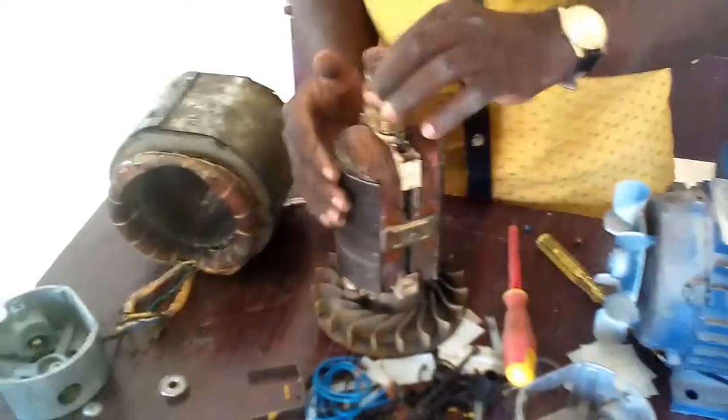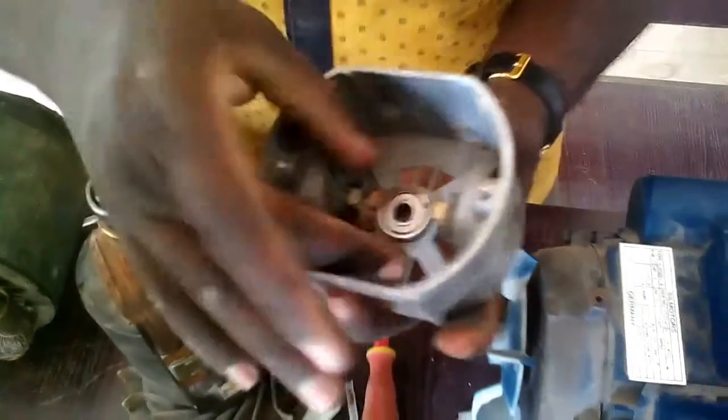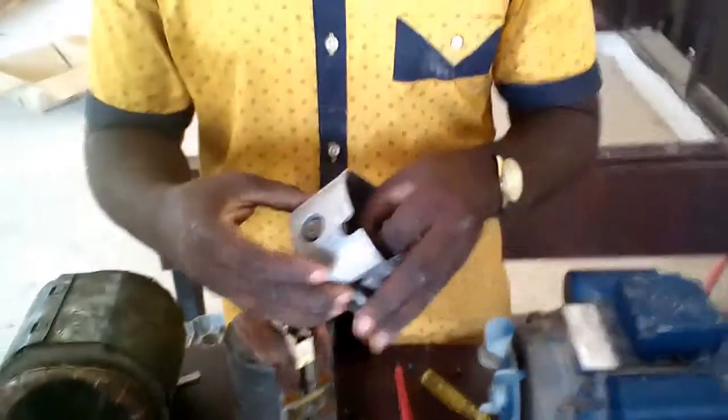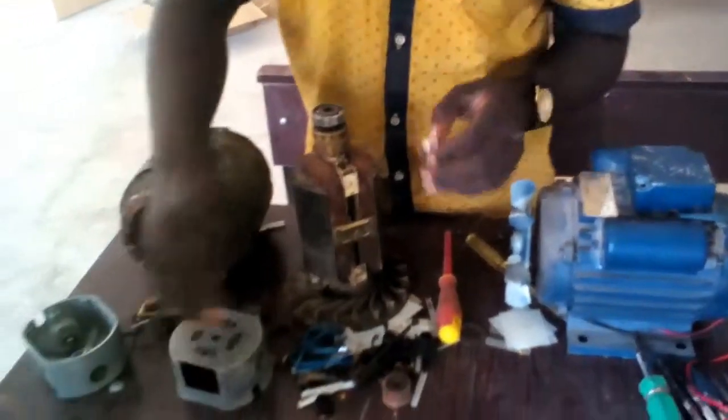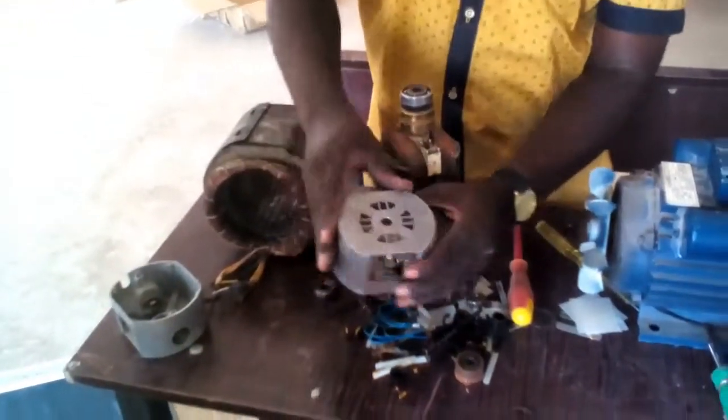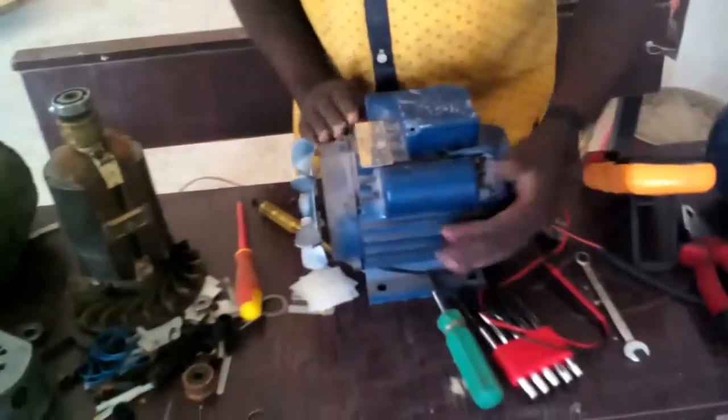They also look at the bearing, and they look at the casing. The bearing and the casing, if they are not properly aligned, the ball bearing will not move freely. Because of that, it will develop excessive heat, which will definitely transfer into the body, the frame of the motor, and then make it become excessively hot.